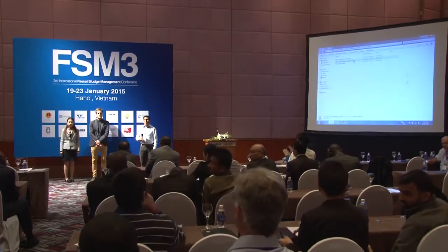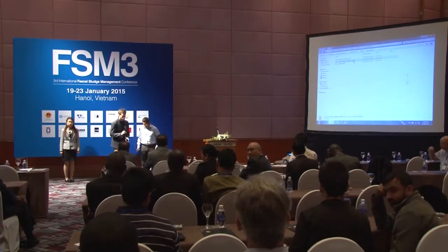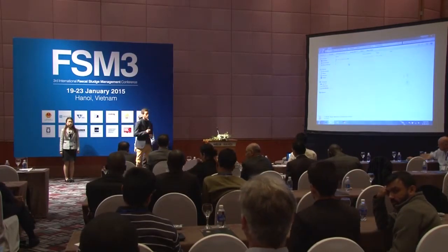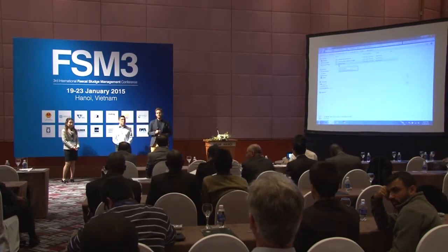Mike Smith from Loughborough, UK. Thank you for your presentation. Just a quick question for Maurice. When you were testing the effectiveness of the conditioners, why did you choose to use the specific resistance to filtration method? I find that a very complicated method, and I tend to use the capillary suction time method.